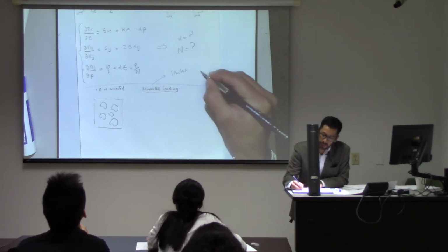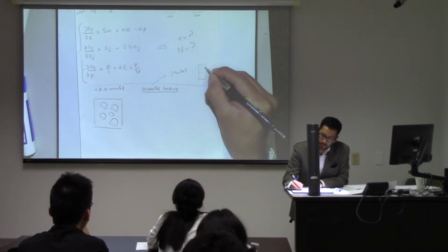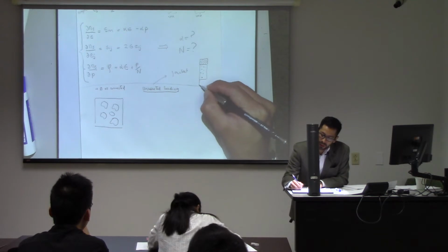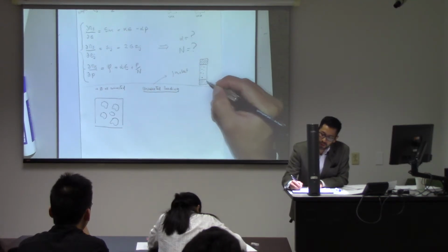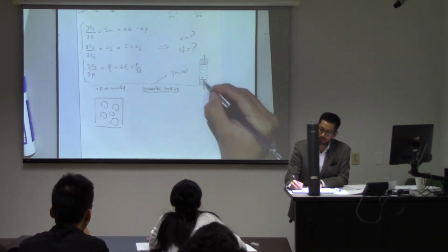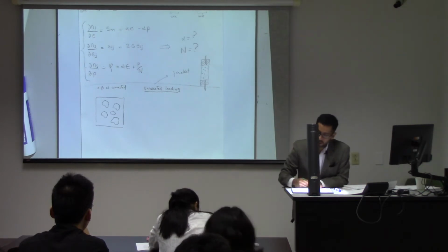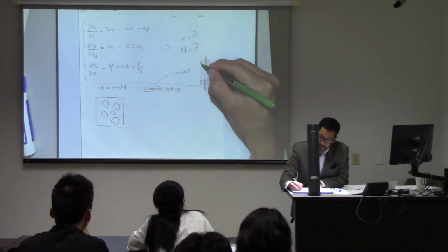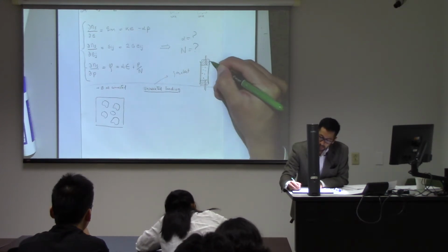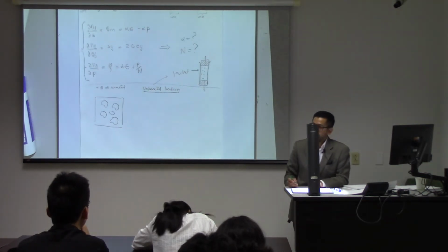If you have a sample with pores, usually you put an end cap here and another end cap here. Sometimes you may have a connection that goes through the end cap to connect the pore fluid with pumps. And in order to apply an outside stress, you put a membrane around it, which is also called a jacket.